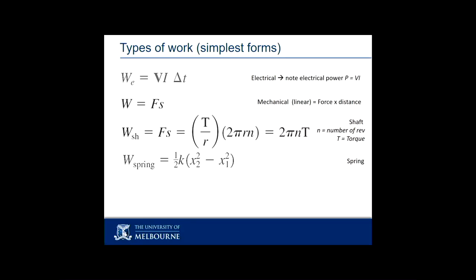By the time we get to the proper end, the hard end of doing thermo, I'm much more interested in whether or not you've understood the first and second law and testing whether or not you can understand one particular cycle. So this is up there as a refresher, as a reminder of all the different ways that work can be done by a system. If these were coming out of a system, if my system produced electrical work, if my system produced mechanical work, I would count them as positive work, and I would count them as a reduction in the energy inside the system boundary.